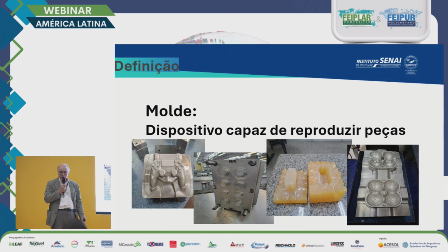The second image is a flat closure, and it's quite difficult to open the mold because it's like a lid. When you think about the lid, you think about this internal thread. How can you release the lid, the cap? There are two ways of releasing. First, we call it forced extraction.